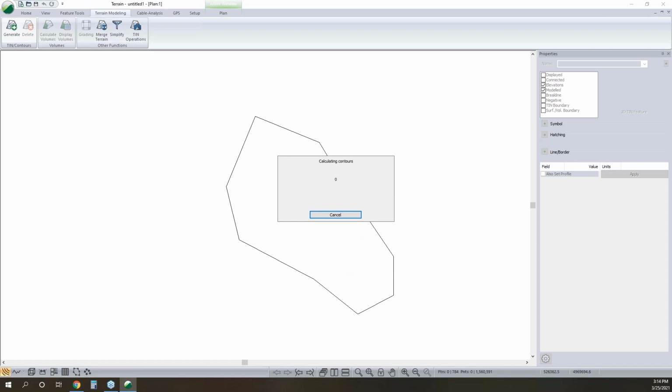And another question that we have come in is, LAZ recommended file format? Yeah, LAZ is a pretty common LiDAR format. Nice thing about LAZ files over LAS files is they're compressed, so they're smaller for sharing, but they are compressed. So when we import, if I had brought in the LAZ files, in this case, it would have taken about a minute to read those tiles in rather than 20 seconds.